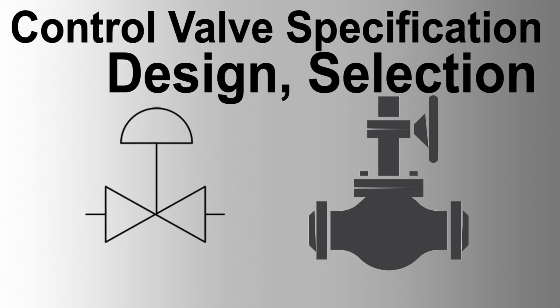11. Valve sizing and selection. 11.1 Sizing standards: control valve sizing as per ISA IEC criteria. Maximum flow, valve opening 80 to 85%. Normal flow, valve opening 40 to 60%. Minimum flow, valve opening 20%.